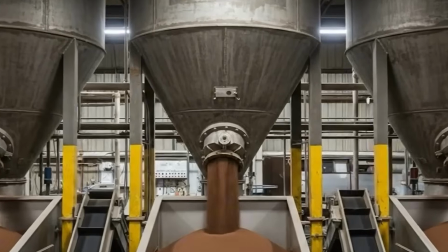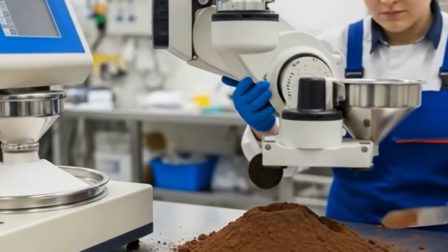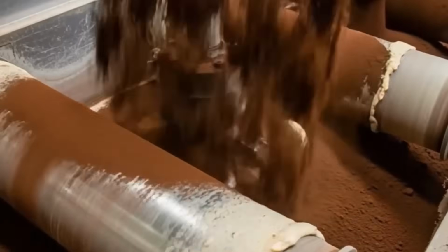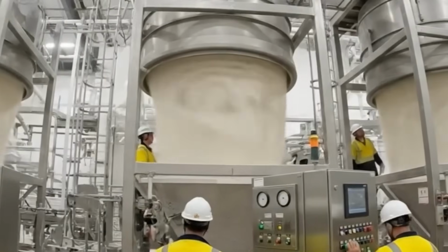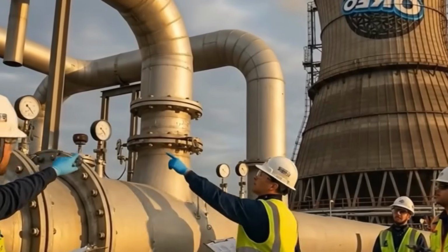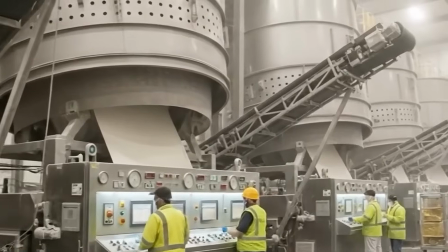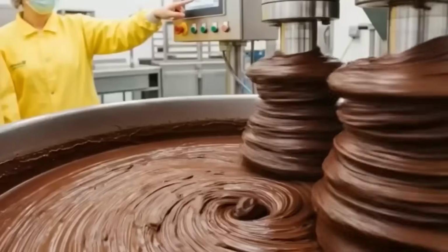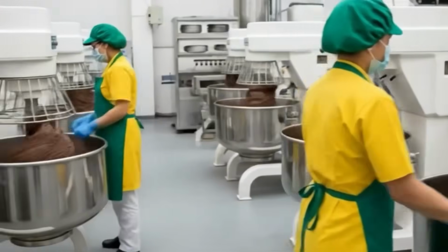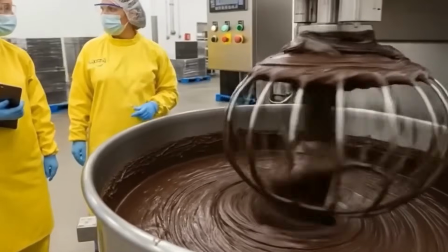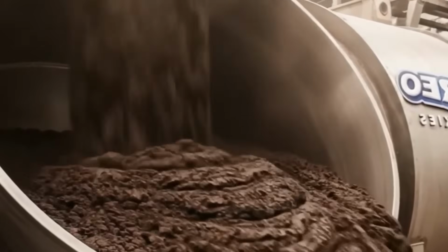The thin dough sheet enters a continuous baking tunnel consisting of 8 to 12 independently controlled zones. Heating is achieved via direct gas-fired convection and radiant ceramic panels. Internal zone temperatures range from 180 to 220 degrees Celsius depending on the position. Air velocity, humidity, and conveyor speed are continuously adjusted via PID feedback loops. Total bake time is between 85 and 105 seconds.